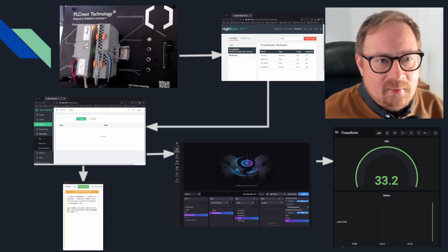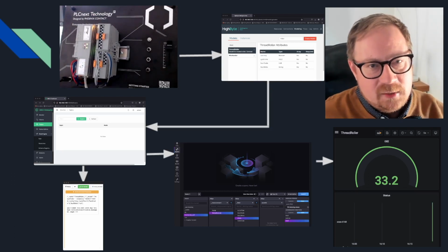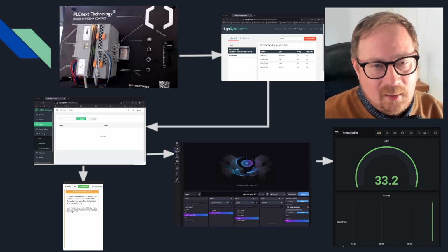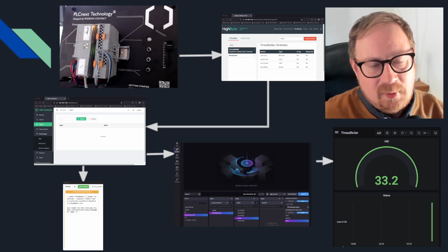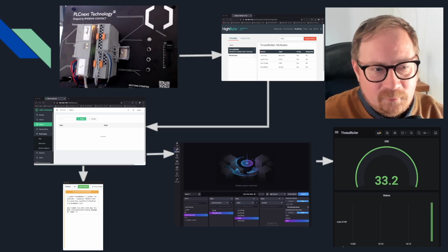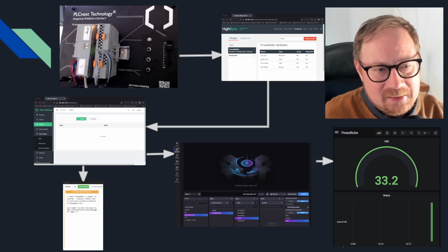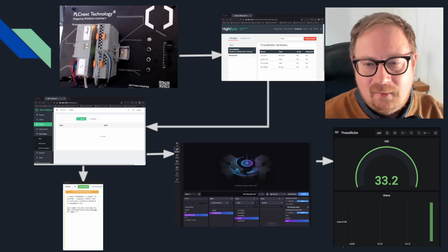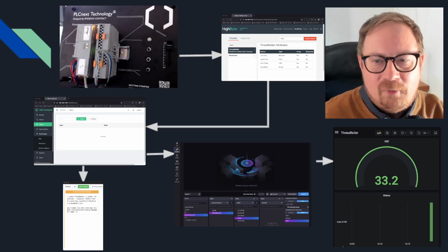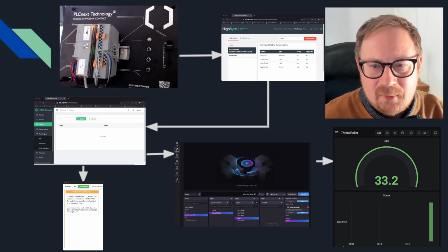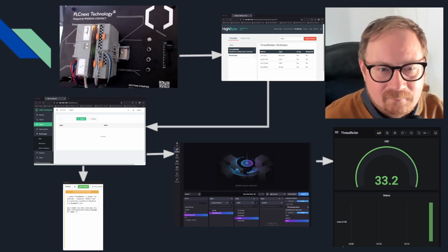So what happened is that the OPC-UA message was received by HighByte, and it created the JSON structure and published it into the MQTT broker. And the reason we know that is because we can also see that on my MQTT client here, that the message was published, and it says thread roller 1, and the information it sends is that the thread roller status has changed. So now my machine is running, the status is running.